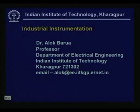Welcome to lesson 24 of industrial instrumentation. In this lesson we will consider piezoelectric sensors. Now as you know, piezoelectric sensors are based on piezoelectric crystals, right. It has a property that if you apply a force across the surface of these piezoelectric crystals, I will get a voltage, and this process is reversible. That means if I apply a voltage, I will get a force also.